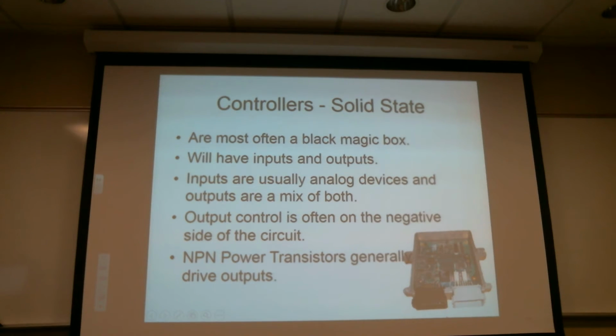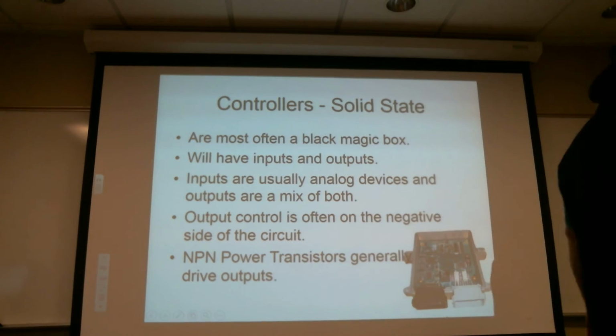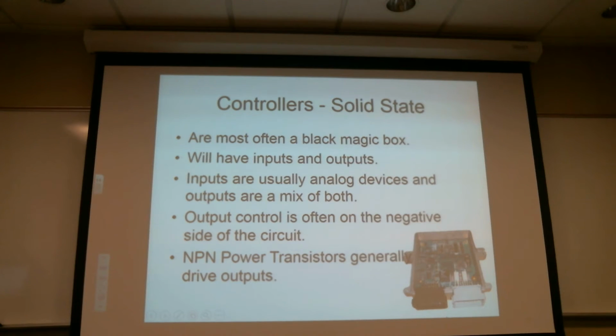Okay. So solid state controllers, we often call them the magic box. In truth, there's not that much magic about them. They're pretty straightforward. They will always have a power and a ground. They will always have inputs, data going in, and they will have data going out, some kind of output. They activate, they turn something on, they do something. Otherwise, why have it? For the most part, the inputs will be either digital in the form of a switch, or they'll be analog, like a thermal resistor device telling you engine coolant temperature, or the amount of light hitting it, or manifold absolute pressure, or whatever.